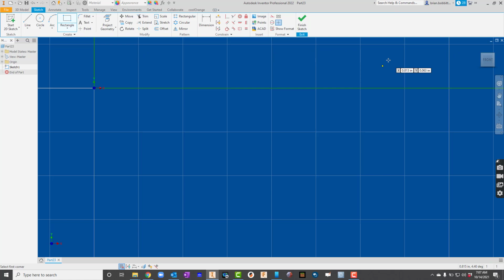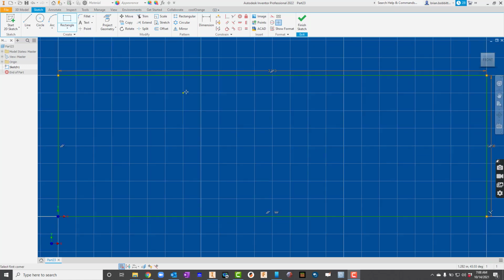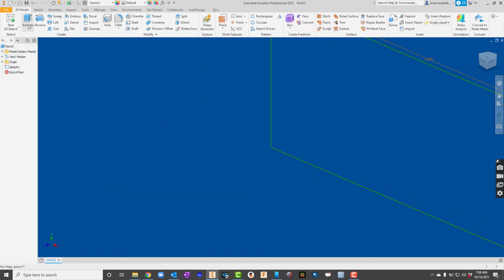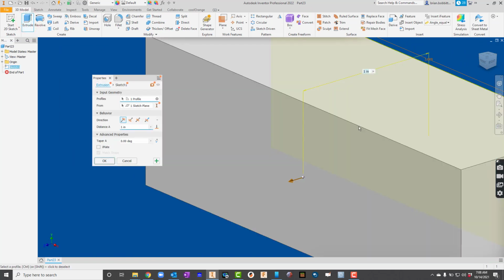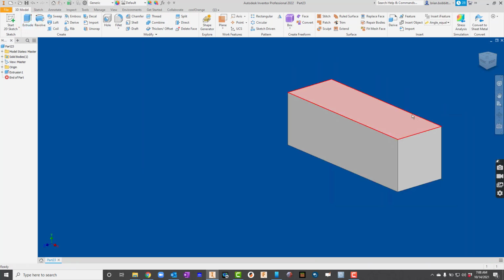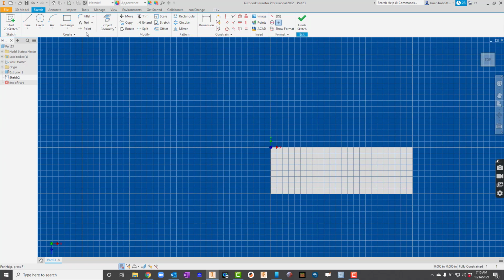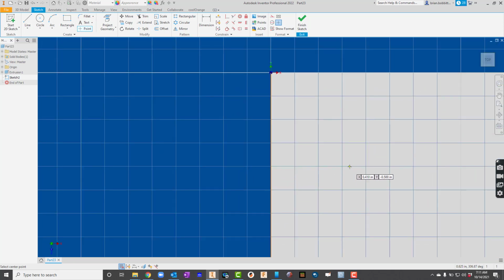All right, and then we can use our navigation panel over here, right? That should look familiar. All right, we'll go ahead and extrude this block, though. I'll hit Finish Sketch and just go up to Extrude. And I'll just keep the 1 inch this time. So I got something like this. So I'll hit Start 2D Sketch here. What I like to do is actually use the point. So I come up here and say point. Then I can find that midpoint again, right? There's that green dot. And I'll come over here and say, all right, there's a point.